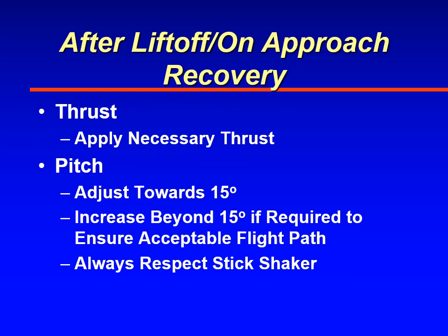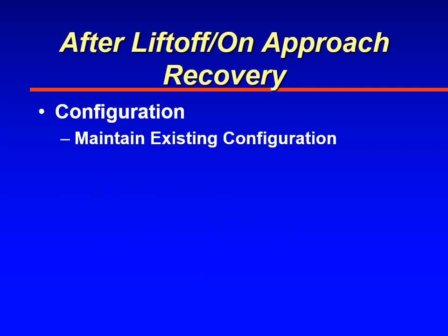If you've just lifted off from the runway and you're climbing out, or if you are on final approach, then you need to apply all the thrust that you have, pitch the airplane up to 15 degrees pitch attitude, but you might have to pitch it higher to get an acceptable flight path. But do not stall the airplane, and that's what stick shaker is. And then configuration, don't bring the flaps or gear up. They want you to fly the airplane and focus all your attention on flying. So leave the gear down and also the flaps where they are.